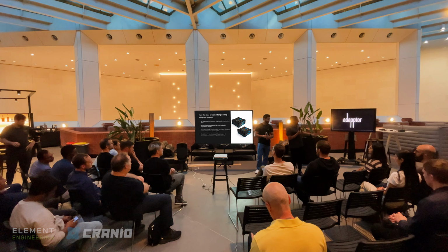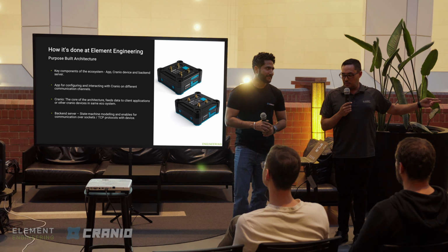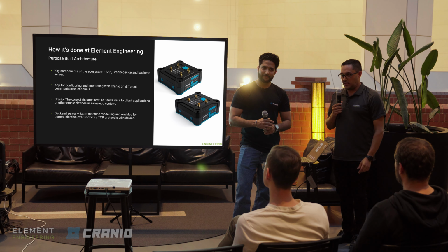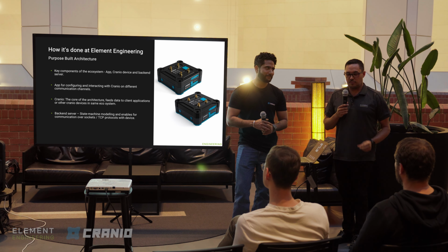We have a live demo here. It's terrifying because it's not actually working at the speed that we want it to work at. But considering the device over there is spitting out data over 4G, going to a server in our office, then visualizing on this web dashboard, it only has 32 kilobytes of RAM and 256 kilobytes of flash. That's not quite enough. The later version of this needs 64 kilobytes of RAM, and that is enough to run our code base at the speed that we want.